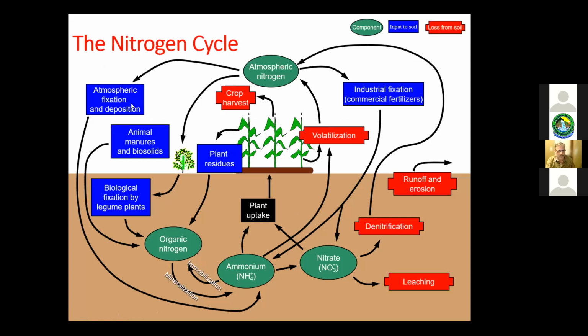Here, I'm just going to minimize the chat thing so I can see my screen. There we go. Okay, so the nitrogen cycle, again, it's good to take a look at this and have an understanding. Most of what wastewater operators are concerned about is ammonium to nitrite. And then it goes into the denitrification cycle. The rest of this is how the whole nitrification system works, but it's important to know it's ammonium to nitrite and then on to denitrification. We will cover nitrification cycles, denitrification cycles, and treatment, as well as phosphorus in later modules.